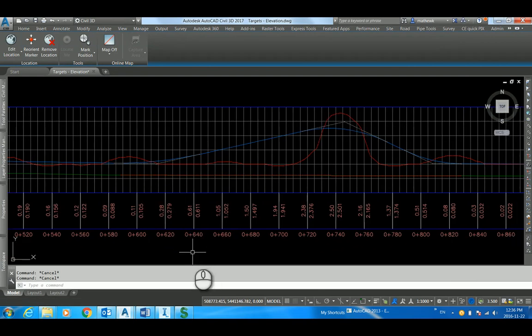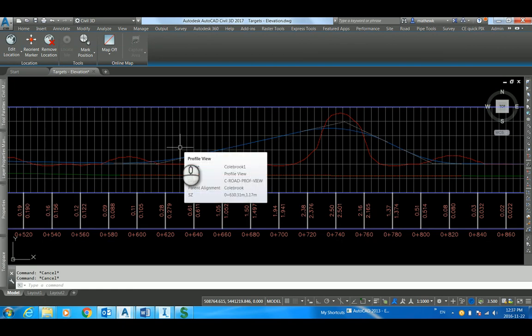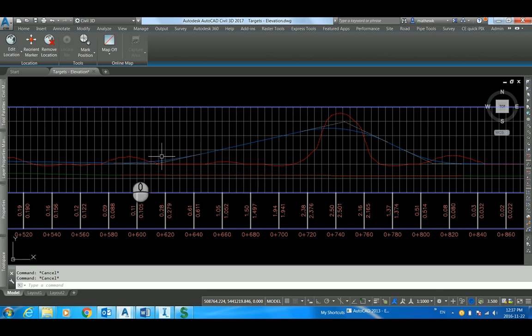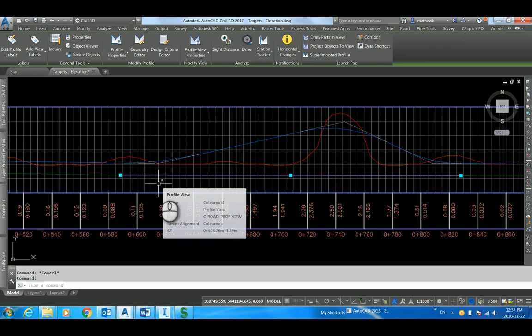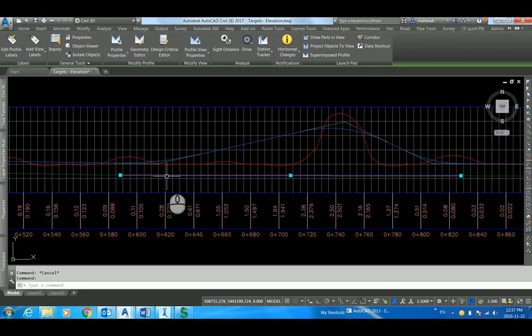Later on in the design, the road must tie into an existing trail. Thus, our road center line goes up and then back down again. Since we want to maintain positive drainage the entire length of the road, we must design a ditch profile in this location. Here it's virtually flat, but that's okay for our design. In this case, we will link this design profile with the associated subassembly.